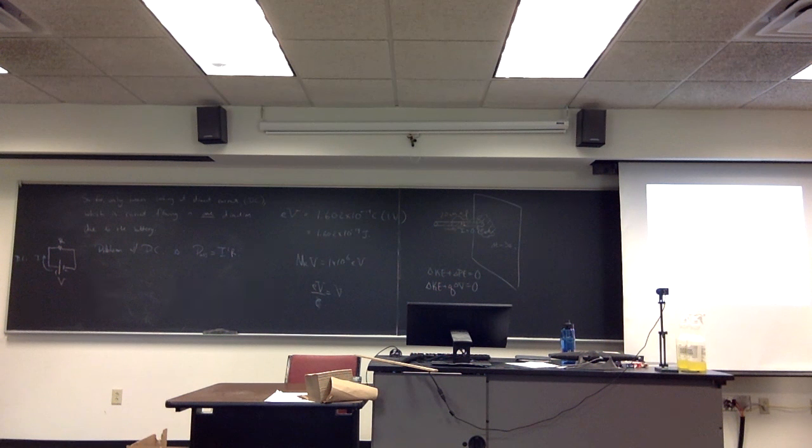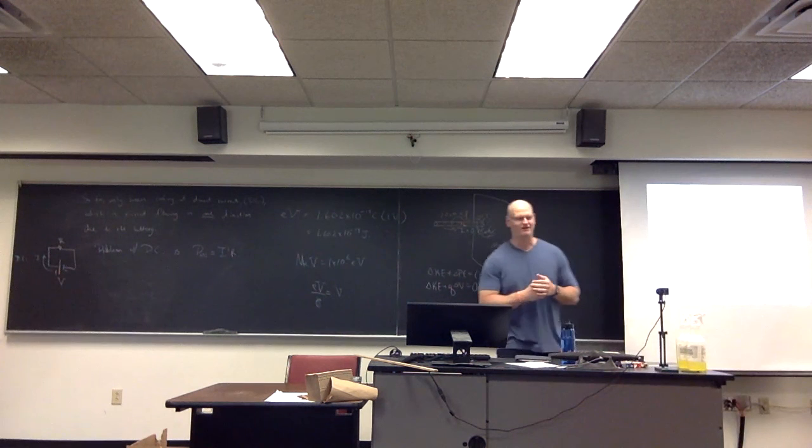So one thing to note about kilowatt hour: remember, watts is a unit of power, which is an energy per second or an energy per time. And then if I multiply that by an hour, that just makes it simply an energy. So basically, the electric company is charging you for the amount of energy that you're actually using. So if you leave this on for 24 hours a day for 30 days straight, so we're going to go with a month equal to 30 days, how much money are you going to be charged by the electric company if they charge you 15 cents per kilowatt hour? So these are all things we're going to find out.